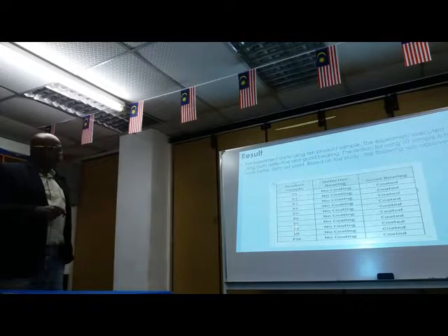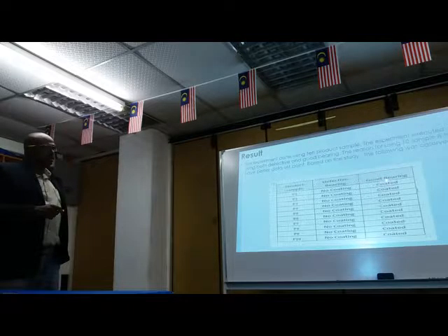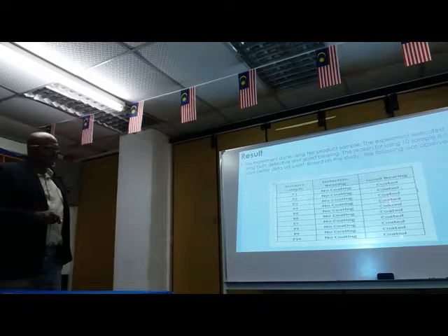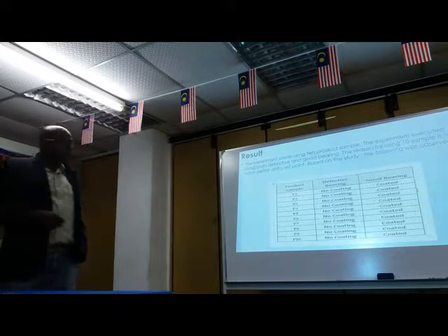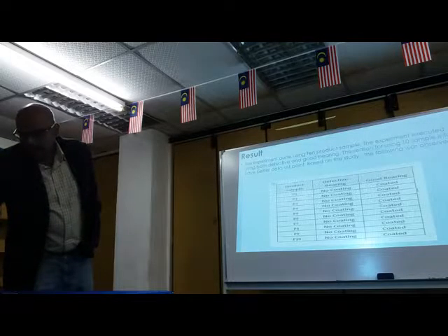So for the 10 products, with the defective bearing, all 10 panels came out without coating. And with the good bearing, which is the normal standard condition, all the panels were fully coated. So from there, we learned that the defective bearing plays a role in the non-coating condition.